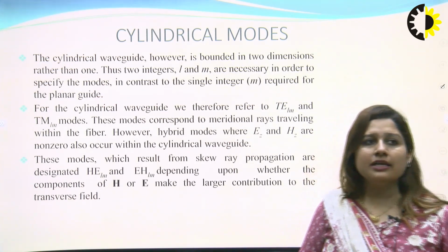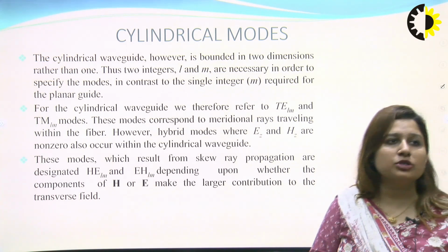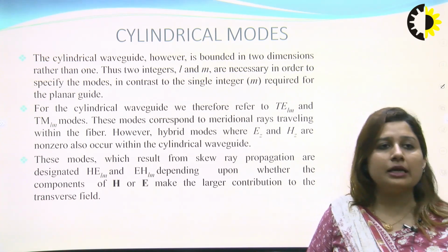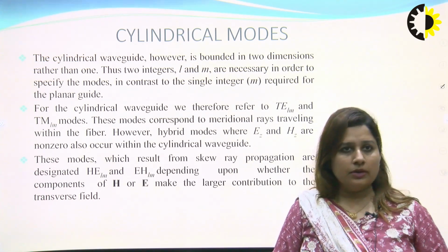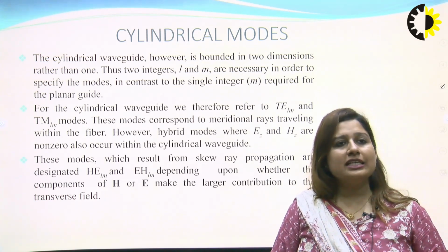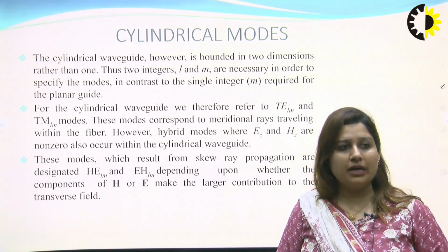If we see cylindrical modes, the cylindrical waveguide is bounded in 2 dimensions rather than 1. Here we consider 2 integers, that is L and M, as compared to the planar modes, which are necessary in order to specify the modes here. So, for the cylindrical waveguide, we therefore refer to TE-LM and TM-LM modes.